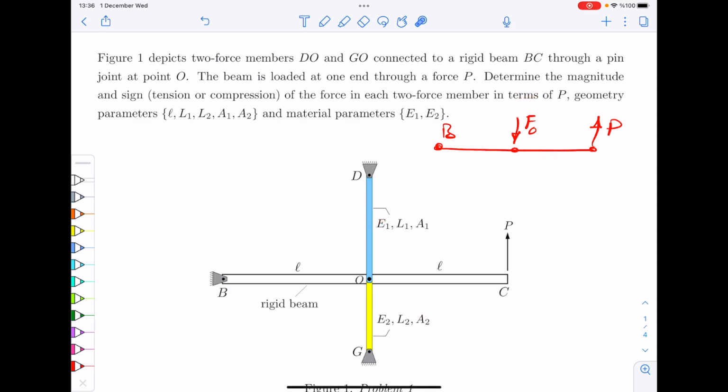That's a different question. But for the first part, for member BOC, you can write equilibrium of moments with respect to B to be 0, and then we can assume counterclockwise to be plus. With respect to B, obviously you have the length, which is 2L times P, that would cause a counterclockwise moment, and then you would have length L times F, that would cause a clockwise moment.